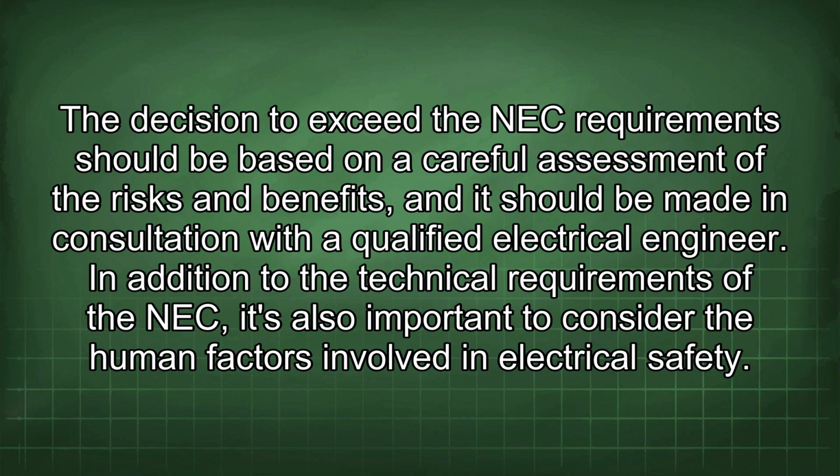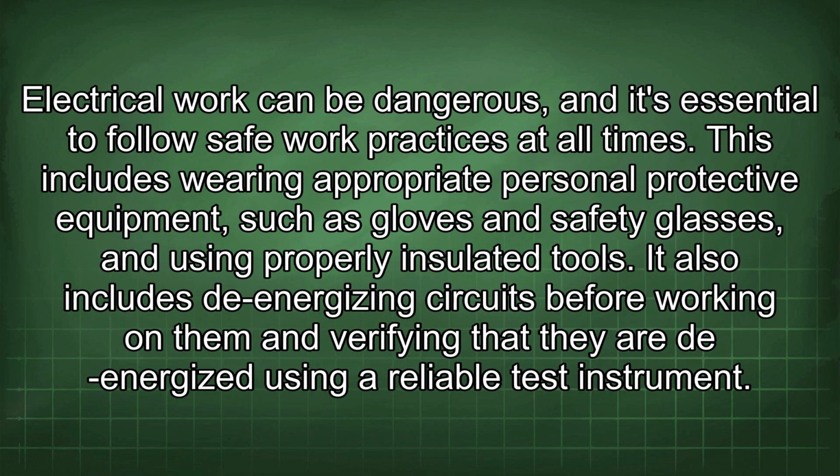In addition to the technical requirements of the NEC, it's also important to consider the human factors involved in electrical safety. Electrical work can be dangerous, and it's essential to follow safe work practices at all times. This includes wearing appropriate personal protective equipment, such as gloves and safety glasses, and using properly insulated tools. It also includes de-energizing circuits before working on them and verifying that they are de-energized using a reliable test instrument.